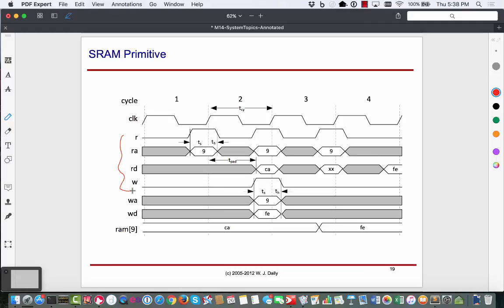These signals out here, and then the RAM will respond. So a typical thing might be I tell the chip that I enable the chip, so there will be some signal for that. I'll have some address lines. I'll have some line for read and write. And so if, let's say, I assert the read line, then the chip will respond with the data after a certain delay. And SRAM is pretty fast, but not as fast as registers.